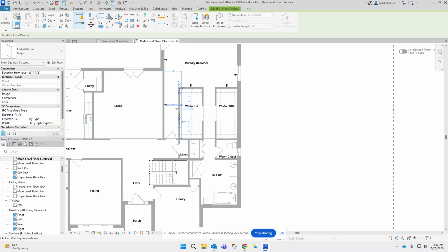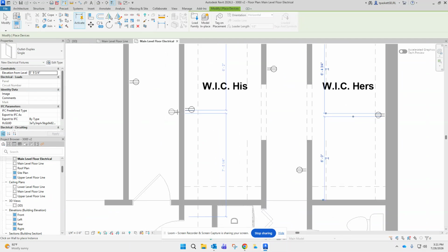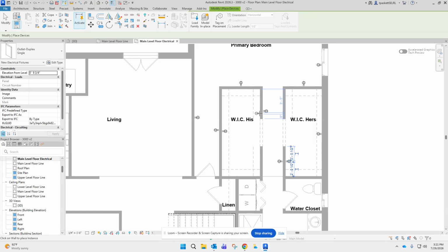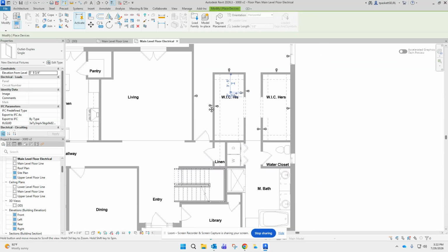And don't forget the hallway going down to the master bath. And I do put outlets on the inside of my closets when they're this large. You might want to steam a tie or iron a shirt. And I'm going to put my outlets, if they're on both sides of the wall, near each other so that the electrician doesn't have to wire twice. They can just go in and use the same junction box for both sides of the wall. It makes things a little easier.